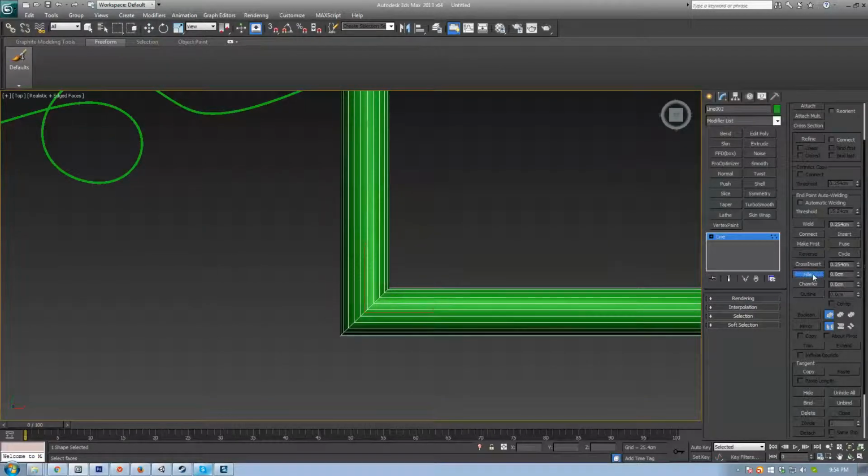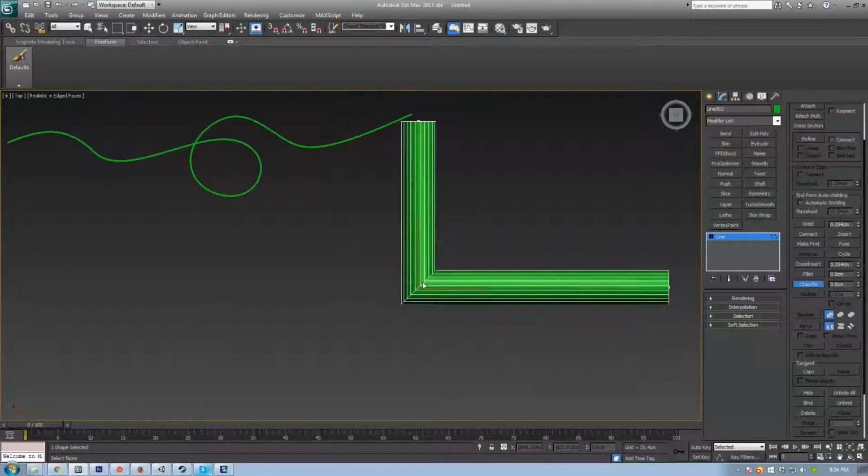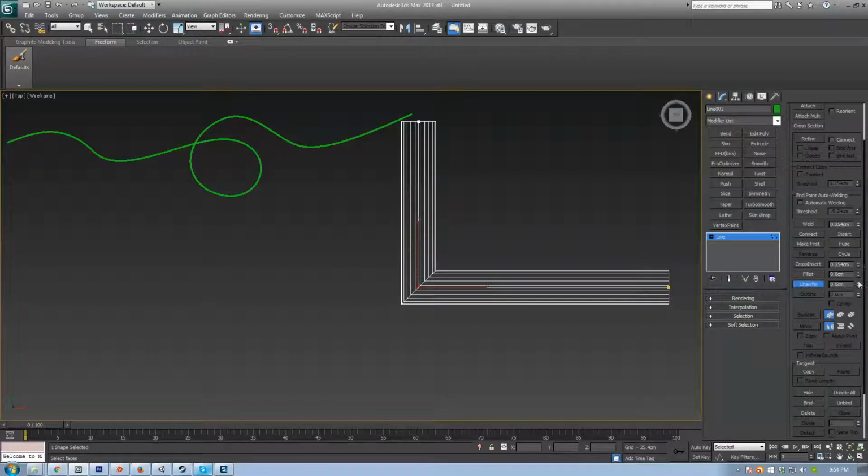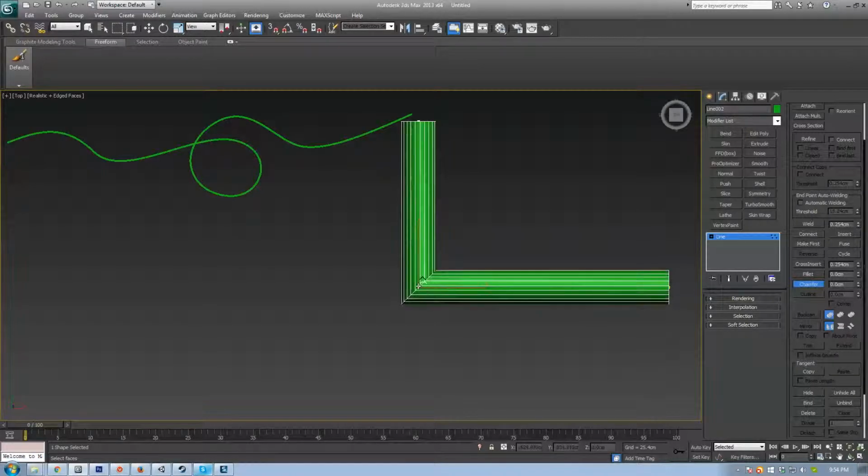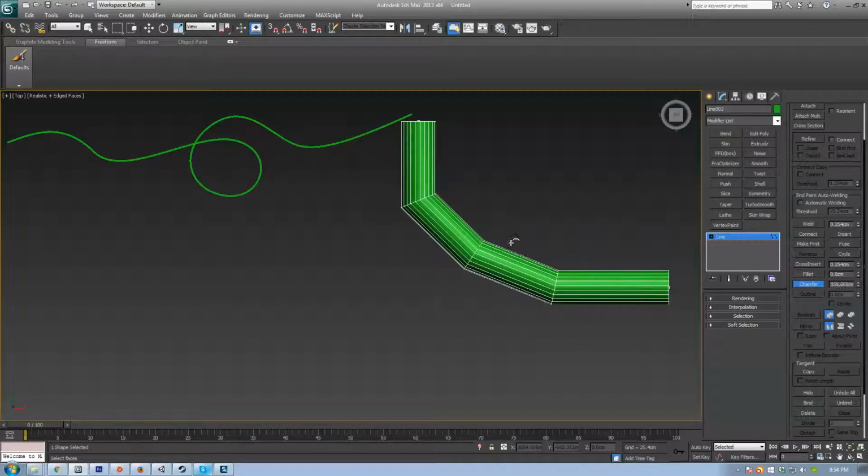Now what that will do is, actually, you know what, let's not talk about that one at first. Let's talk about chamfer. Chamfer is a simple one. You can select a vertice, and you can either play with the numbers here, or you get this little tool as long as chamfer's on. And you'll see there's like this arrow with like a white thing on there, and you can click and drag over your verts, and it'll just chamfer them. It'll add a nice 45-degree angle, because it's the halfway mark between the 90. So you add some nice corner angles in there if you wanted to.